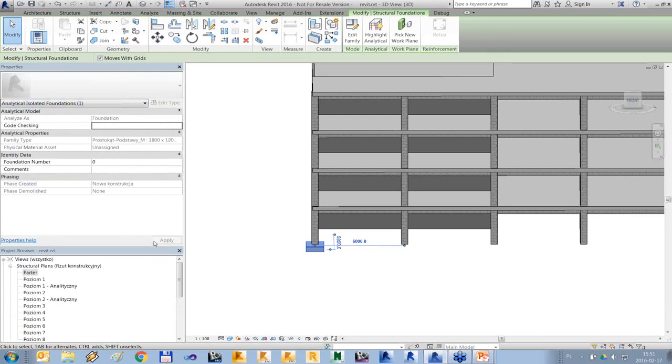So by playing with the analytical support, you can select different degrees of freedom to be free or fixed, and also add elastic coefficients. Or in case of using standard 3D model objects, you may see their settings in the properties window, as a default fixed.